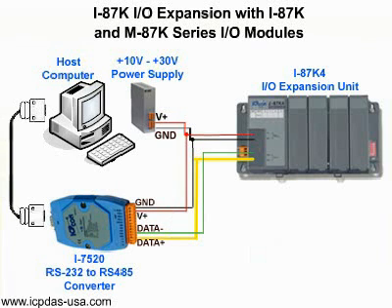RS-485 is the only communication interface of the I87K I/O expansion units, which are used to expand I/O modules. You can configure its I/O modules with DCON Utility. You can connect your computer to the I87K I/O expansion units as you would the 7000 modules.